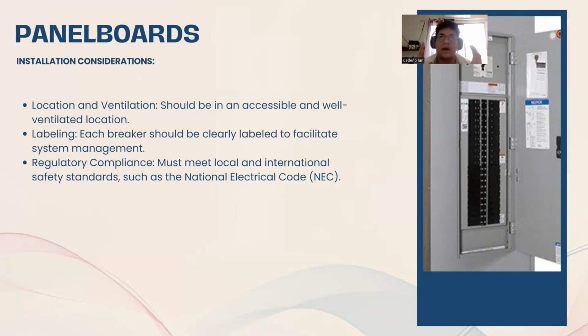It's very important to have a good location and ventilation area for the panel board. For example, we don't want a panel board in a difficult location of the house. Every person should be able to get to the panel board. If a breaker is bad, you put it off and it's safe.